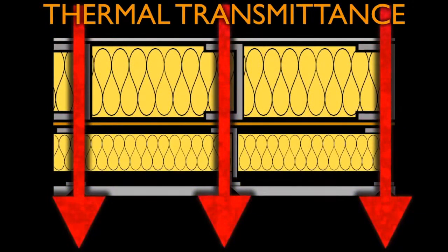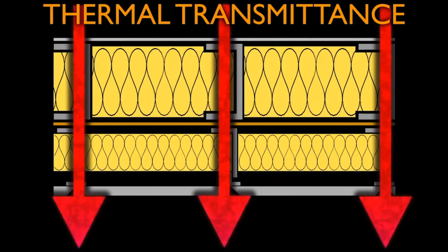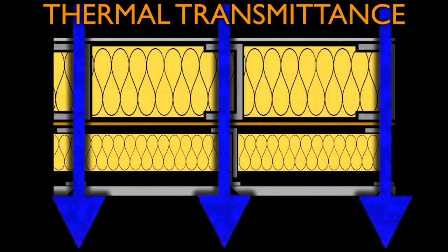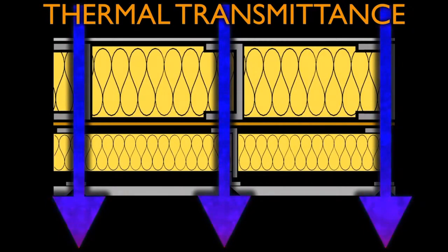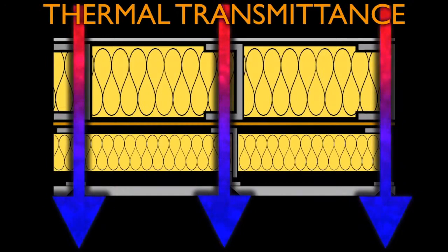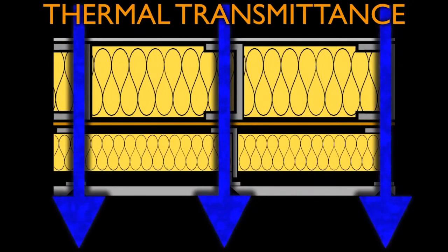Locations where structural elements intersect insulation are known as thermal bridges, and in these areas, heat typically flows faster than through the insulation. U values are therefore adjusted to reflect this, and the methods for doing this are given in the ISO 6946 standard and the BRE guidance document, BR 443. Non-repeating thermal bridges, such as floor and roof junctions and corners, are also adjusted for. The heat losses associated with these features are called psi values.